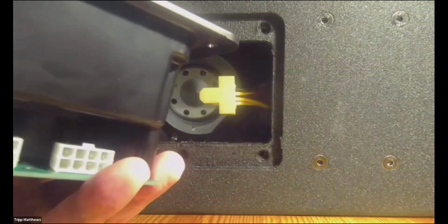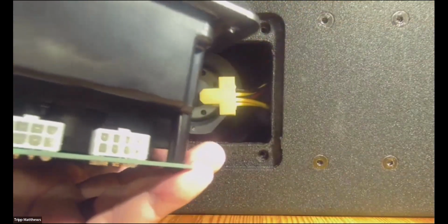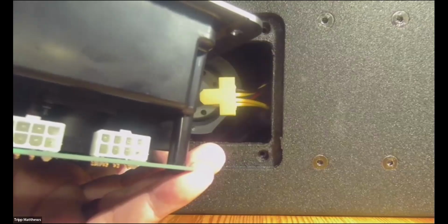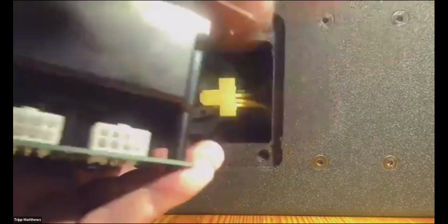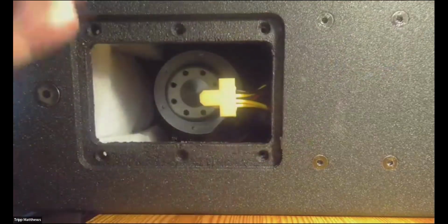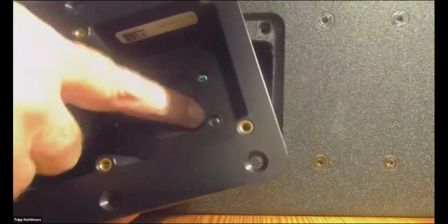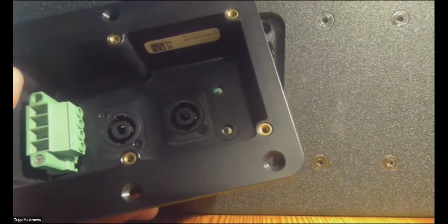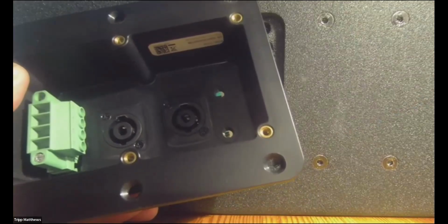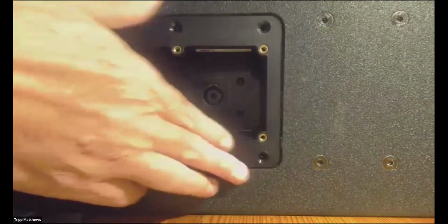And what that is, is a connector, as you see here in the back of the speaker, and then 2 Molex connections on the board. And really all you do is just move that connector to where you want, push it in, have it snap on. You will need to remove a little tab to get it off. And then when that is actually connected, these 2 tabs, one or the other, will show you which mode you're in, just in case you're not sure where the speaker is by default. And that's really all is needed to get you into biamp mode.